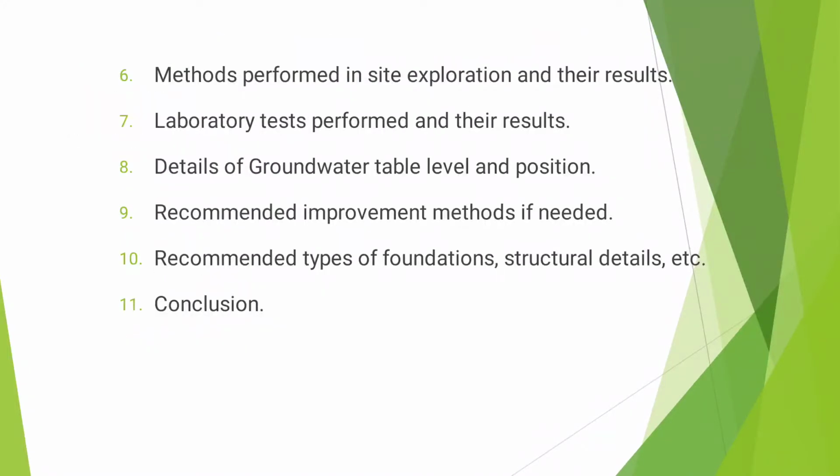Next one, methods performed in site exploration and the results. Method means the type of boring and the equipment used, which are explained in detail. Next, laboratory tests conducted on the soil samples obtained by the boring method. Next, details of groundwater level positions.